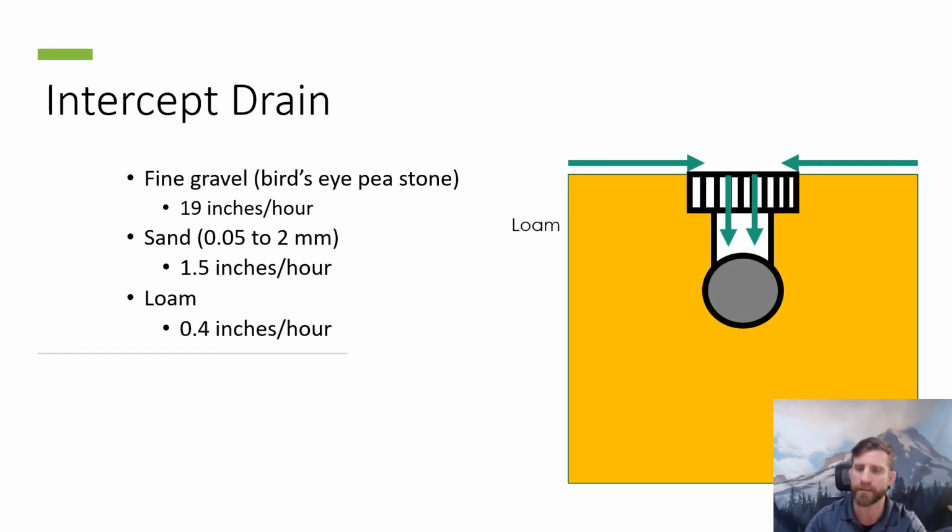So with the catch basin system now, what we're doing is instead of having the fine gravel over top of the drain tile, we just have this grate system, which the water comes across the surface, it finds this grate, and it falls through the openings of the grate into the catch basin, and then the catch basin is tied to a drain tile, which allows for very rapid surface drainage once it makes it to this catch basin here.